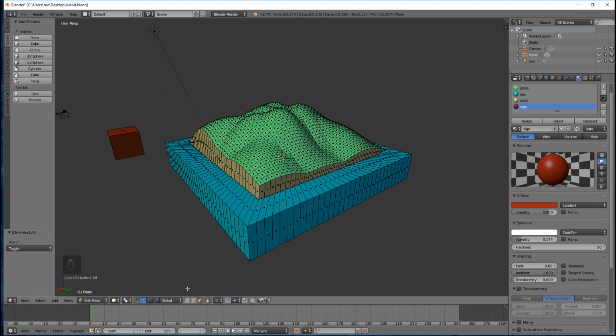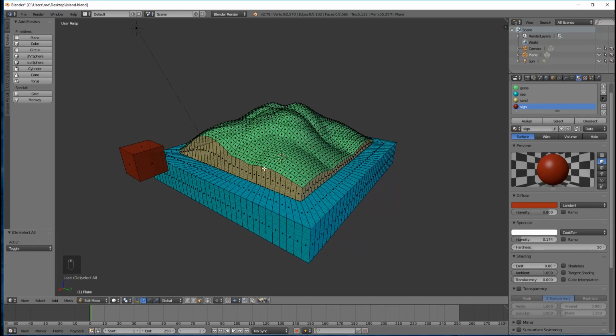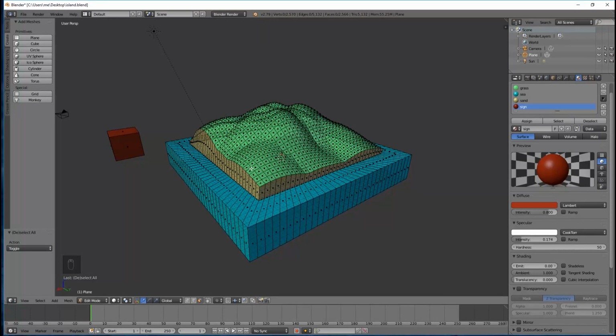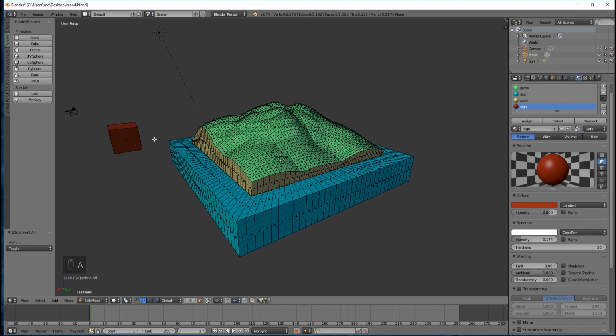So the first thing we do is come down to the bottom here where we have these three little cubes that we've used before for the different selections, and immediately after the cube there's this, I think it looks a little like a drone or something. It's a cube with a little circle in every single corner, but that is limit selection to visible. If I click it, you'll see that we can now sort of see through the models. They are slightly transparent. Looks a bit weird at first, but that means now that when I select parts of my model, I can actually select the back and the front, so I can select all of it rather than having to revolve around it. Now that looks a little bit odd, and it's not the best way of looking at your model, but it can be useful. So that's the first thing we do.